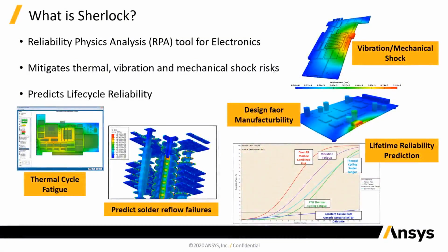Ansys Sherlock addresses the question of printed circuit board reliability upfront during design. The goal is to reduce or even remove expensive PCB test iterations by addressing the potential issues before physical prototype, and further to ensure and enhance the reliability of your PCB product for its projected lifetime of operation in the field. Sherlock uses a combination of physics equations, finite element analysis, and materials knowledge to provide this reliability calculation.